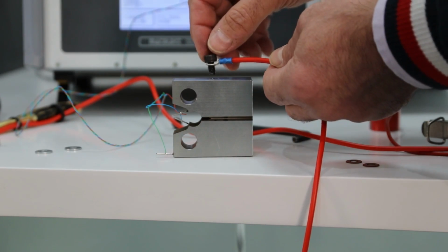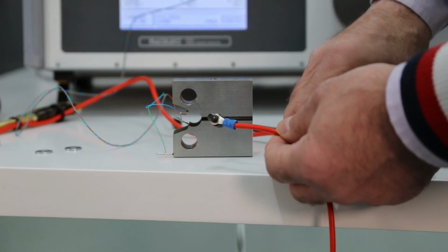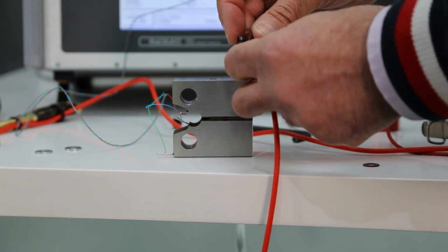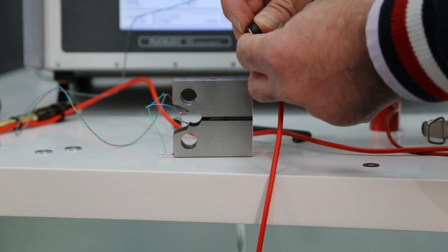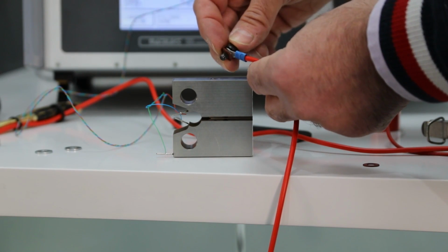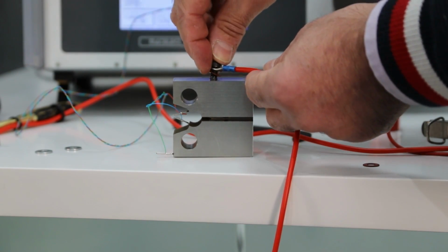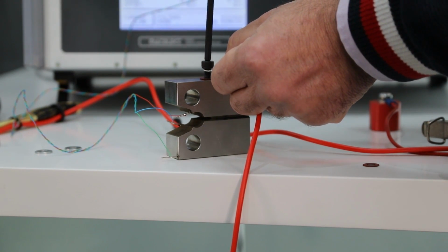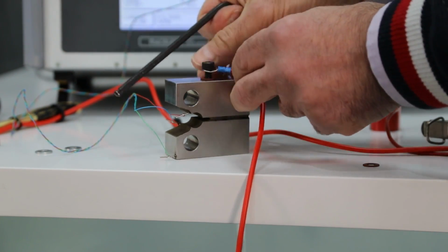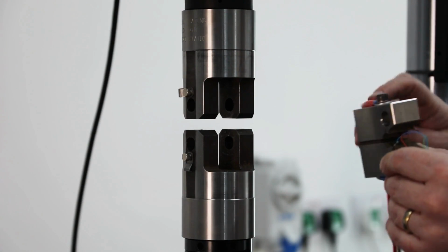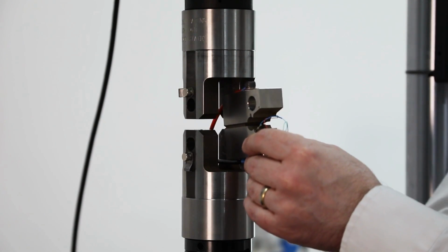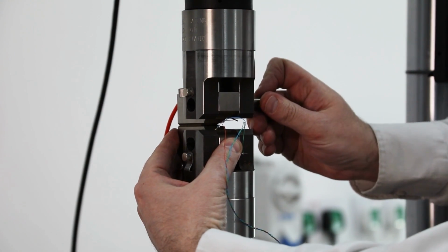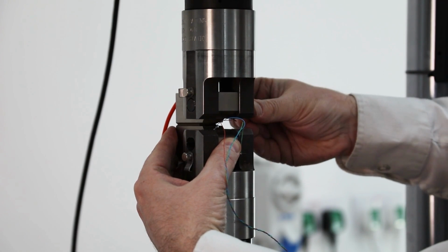The current is going in now. At room temperature, low temperature, you can use screwed connections, and you can deal with very thick cables that way with solder tags. If you're doing high temperature work, then you'd have to go for spot welded connections, beefy spot welder, and that works quite nicely. You can see the fiber washer in there that ensures that the current goes into the specimen where you want it rather than elsewhere in a non-discriminate way.